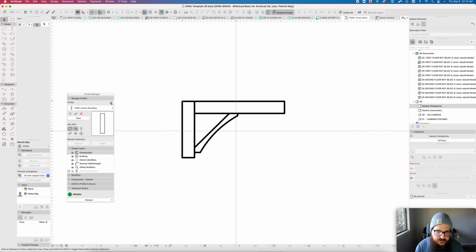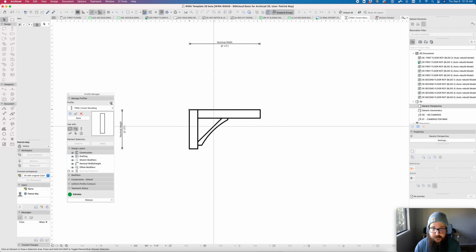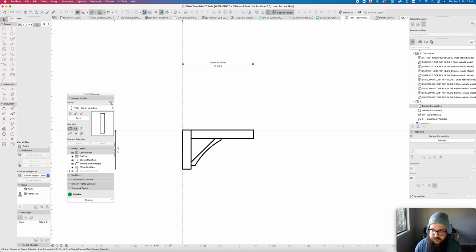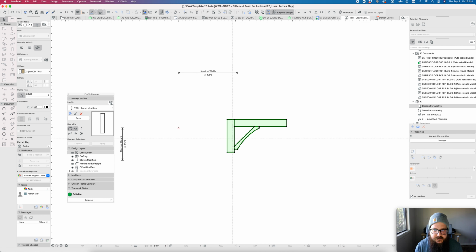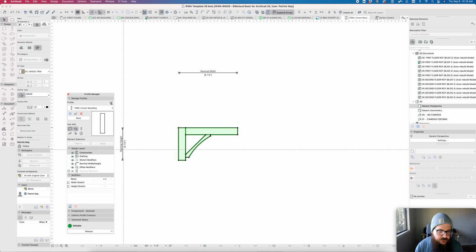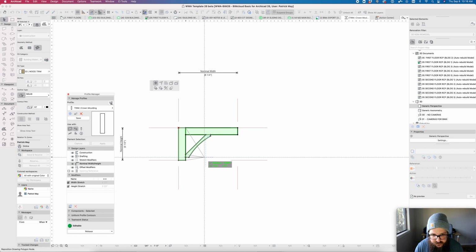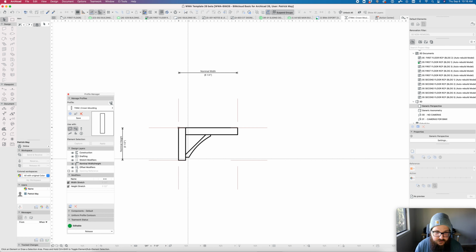It can be, you know, in the case of some of our remodel projects in San Francisco, some of these profiles get really built up and complex. The origin or reference line of this profile is the 0, 0 point. That's this point right here. If I move this off to the side, it actually shows up kind of with that red surface right there. There are modifiers in the profile. There's stretch modifiers I can see right here, but I can also apply those so that the profile can be stretched in the model. It does stretch it proportionally. So like if I change this width in the beam settings from 6 1/4 to 8, all of these distances here to here, the thickness here, all stretch proportionally.